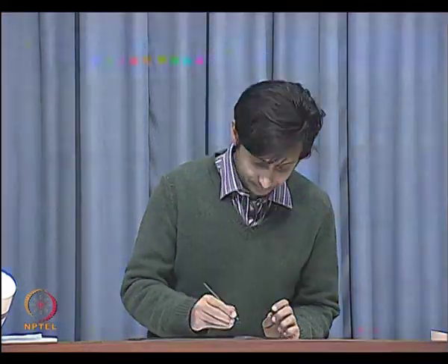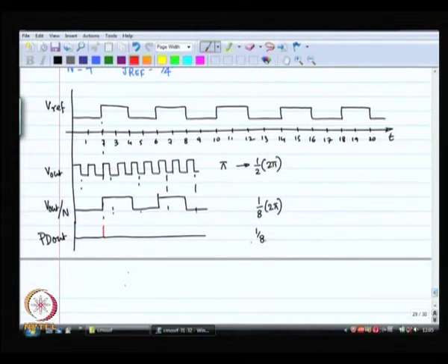That means that the output of the phase detector is going to see a brief pulse over here, both for up and down. Now, if the DAC was ideal, this pulse is irrelevant. Unfortunately, the DAC is not ideal.